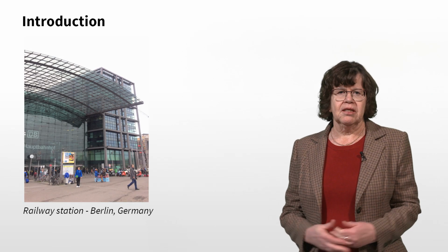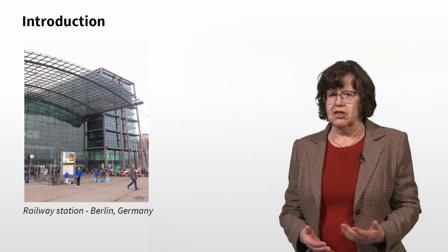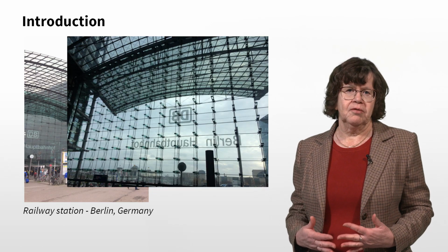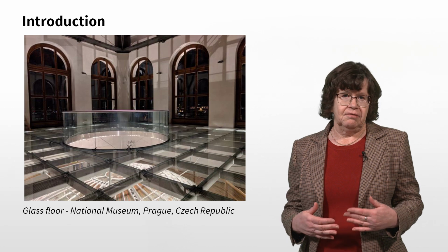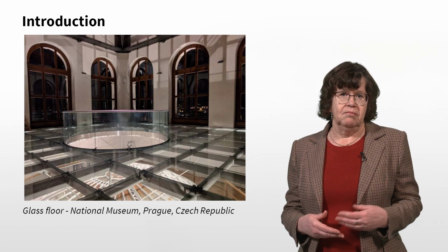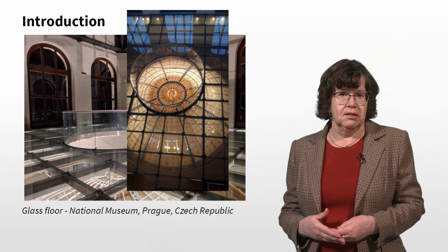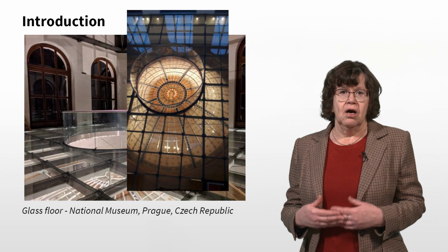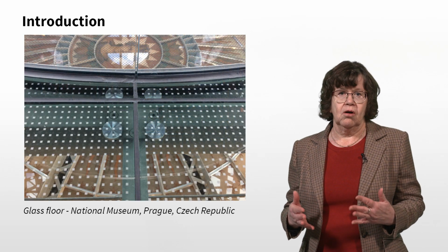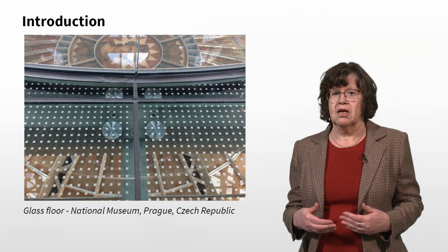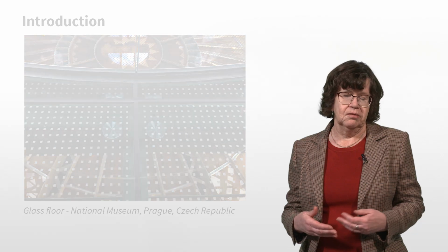The development of laminated glass and its use in the building industry made it possible to design transparent glass structures. These structures are commonly manufactured from laminated glass, which offers high load capacity and safety. However, the design must take into account the polymer interior that is inserted between the glass plies. The material properties of this interior influence the behavior of laminated glass, especially under loads applied perpendicular to the surface of the pane, such as floors, railings, roofs, and canopies.